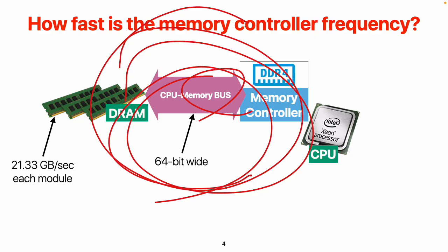So first of all, to trigger a write operation, you need a few cycles in the very beginning, and you have to send some signaling. You need some kind of signaling saying that, for example, if you see this, this is a write, right? So this is like a very initial signal. And then you can start sending your data.